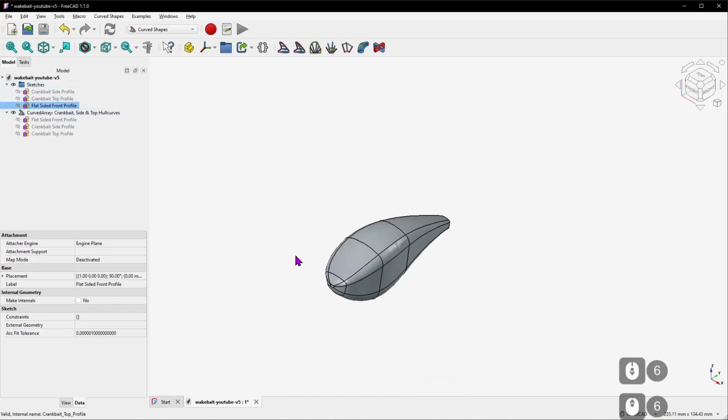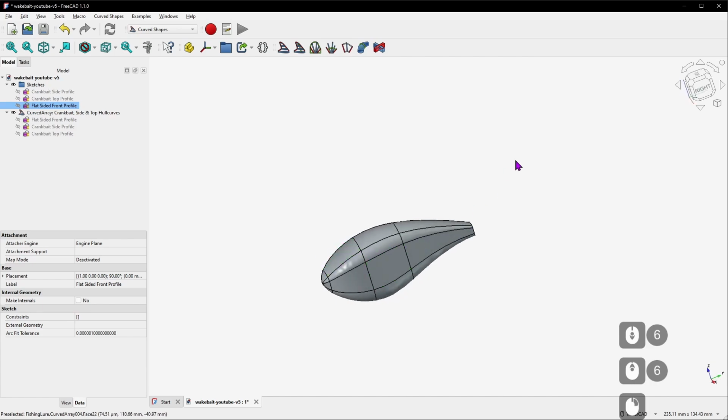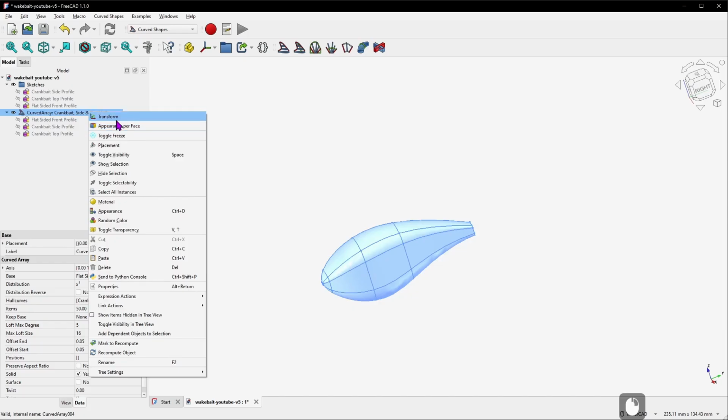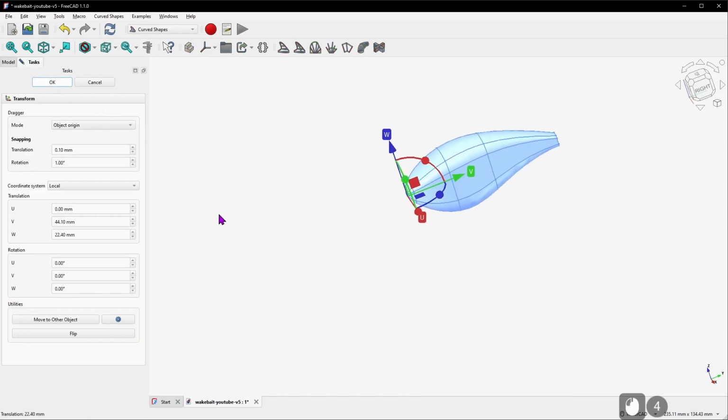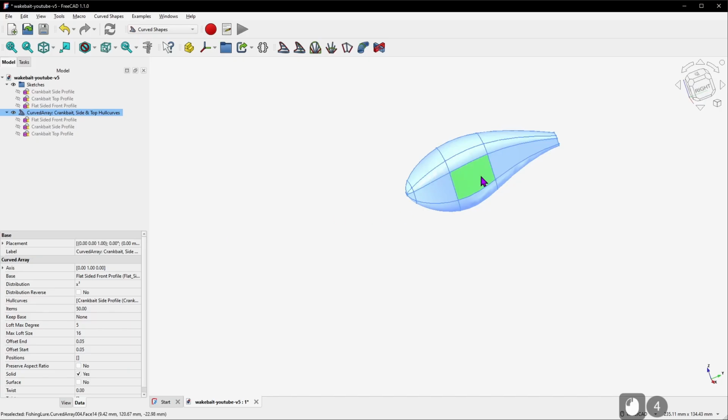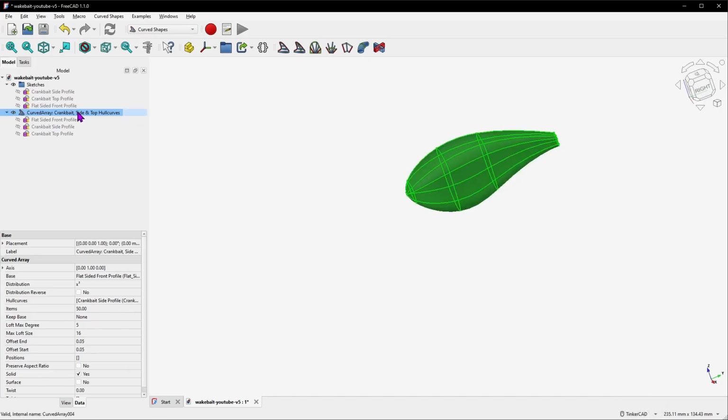And the other thing we're going to do is, because there were originally 5 lures in this example, I built them all on the origin. I built them all in one place, but then I transformed those objects. I right-clicked them and moved them around so that I could lay them all out. And when you do that, it transforms only the object that you're dealing with, but not its dependencies, the sketches. So the sketches are all where we need them to be, but this object is not.